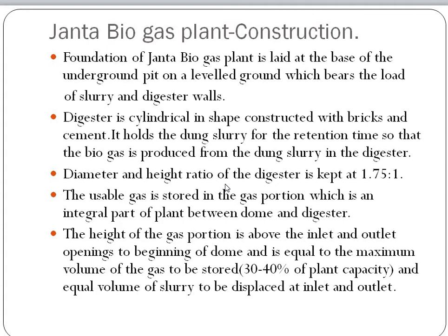The diameter to height ratio of the digester is kept at 1.75:1. The usable gas produced in the biogas plant is transferred to the utility by the gas valve.